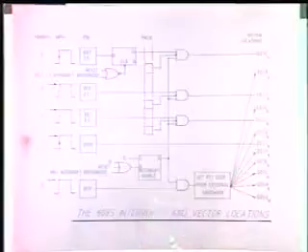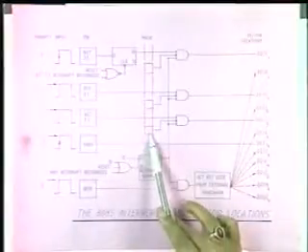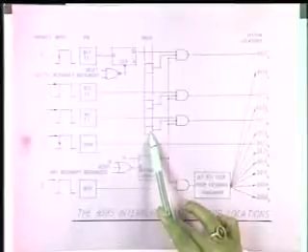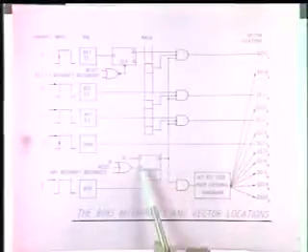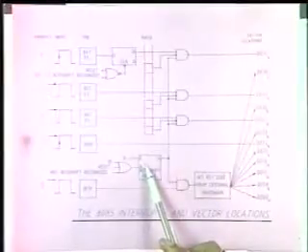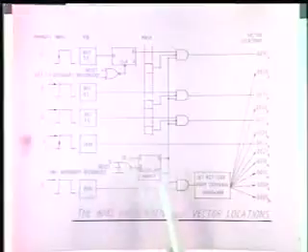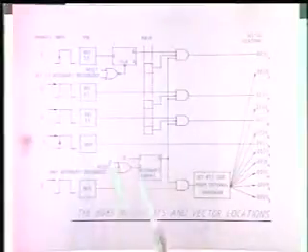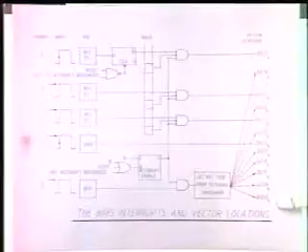So for an interrupt, what happens? What is the first requirement? You have to energize the corresponding bits of masking, plus you have to enable the flip-flop by executing an interrupt enable instruction, and then the corresponding interrupt will be responded to, and once you respond, it will go to this unique vector location or vector address.